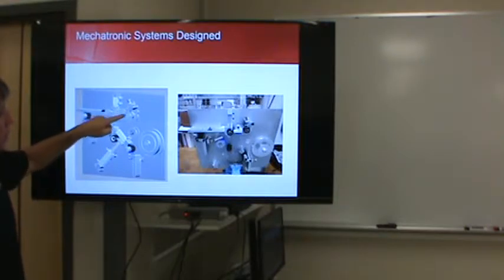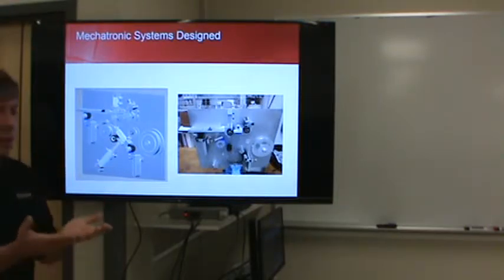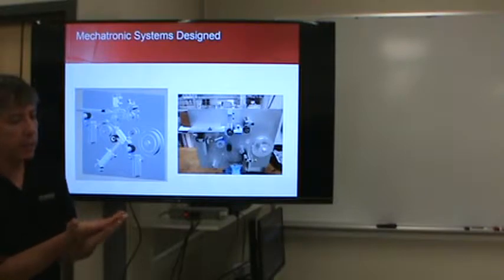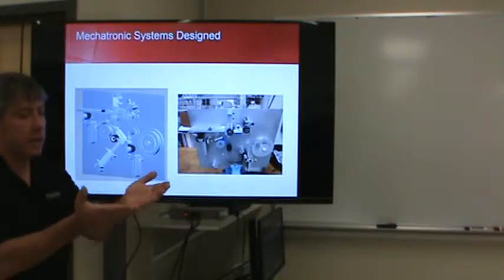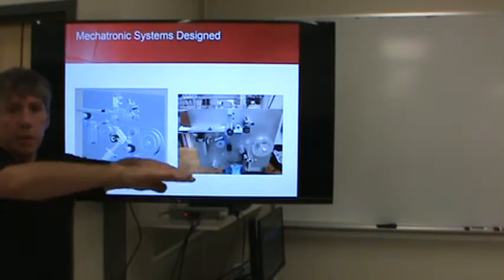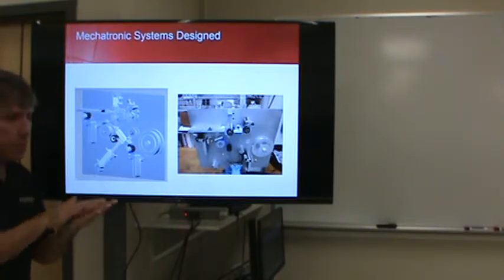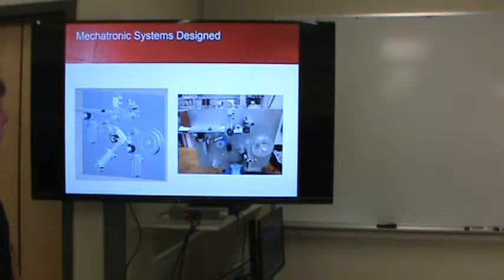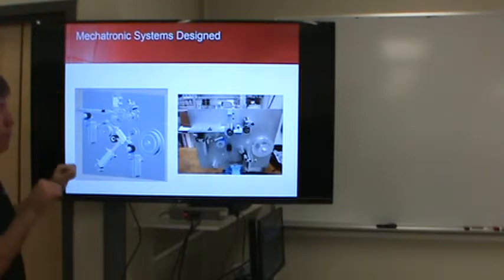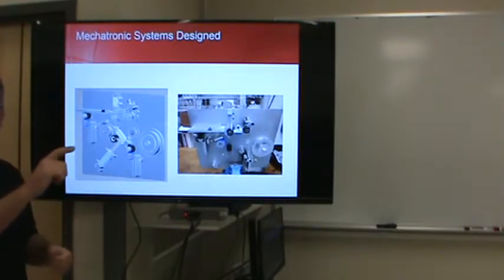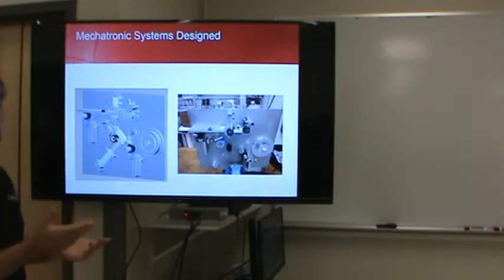I designed a custom tool here that basically just, as the lamp went in, it was actually bent a little bit, and the sides went up to fold the tape around all in one motion. It worked really well. And there's a pinch roller then to just pinch the tape on top and connect it all. The hard part was actually the fact that each of these lamps were going to be fed in by hand. We wanted it set up so when you fed in a lamp, it just applied the tape and sent it out and was ready for the next one.